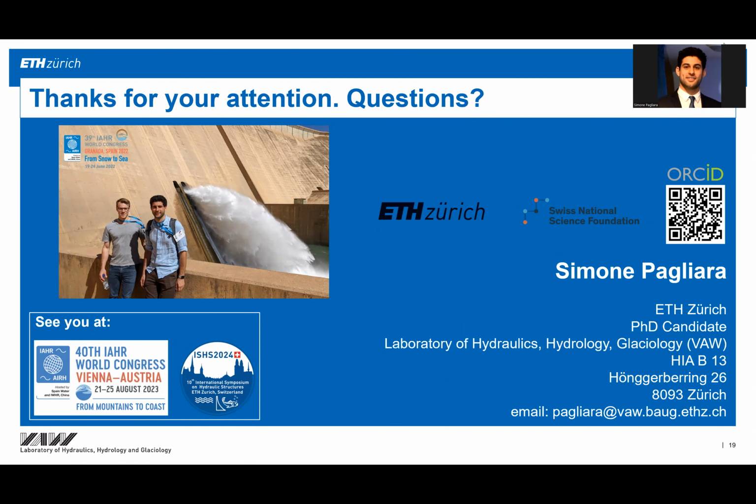We will focus on cavitation, but the point will more be the effect that our tunnel roughness, profile transitions, and aerators will have on the flow aeration, because it has been proved by many studies that you just need 4%, 5%, 6% of air close to the tunnel invert to completely avoid cavitation or to limit it a lot. So the main focus would be to study the aeration in the layer of flow very close to the invert.